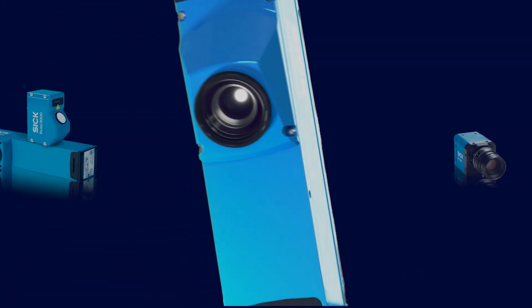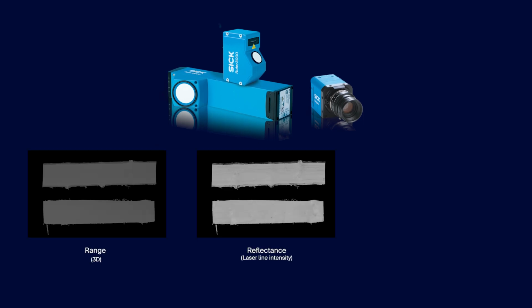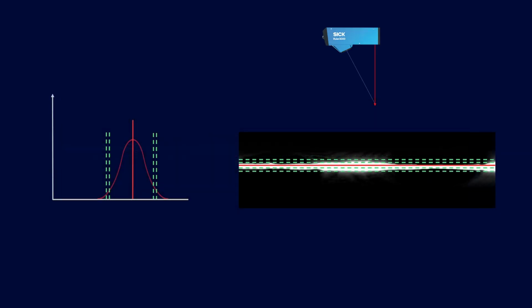To understand what Surface Plus is, we first need to understand that our 3D laser triangulating cameras can capture three types of data: range, reflectance, and scatter. Surface Plus is an imaging technology based on the scatter data. Scatter data is normally used to measure how much the laser light is spread or scattered in different materials. This is done by measuring the intensity of the laser at a distance from its peak.